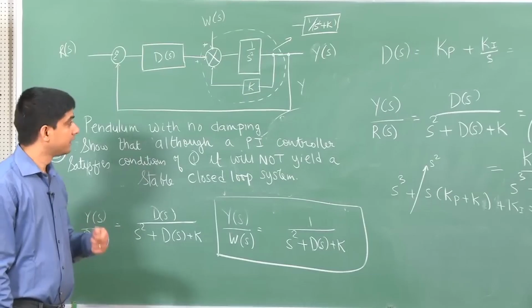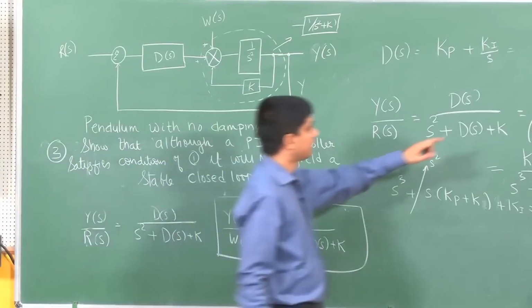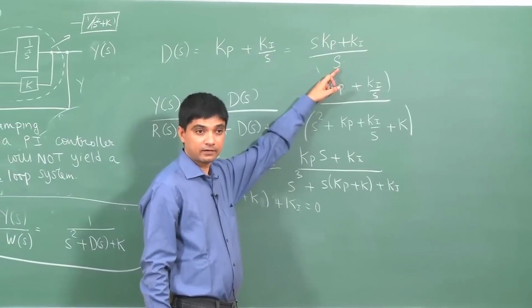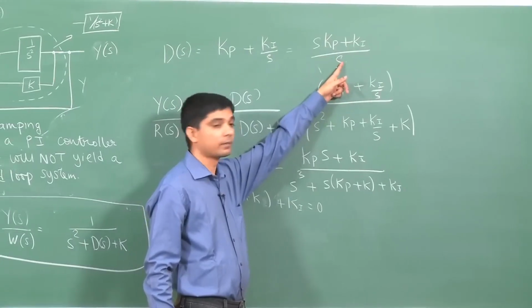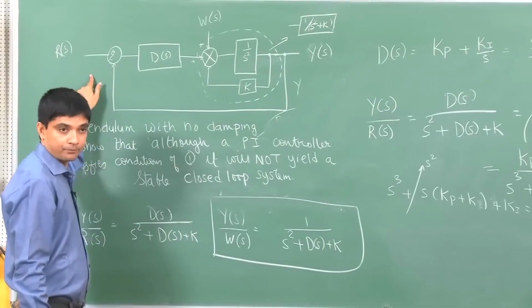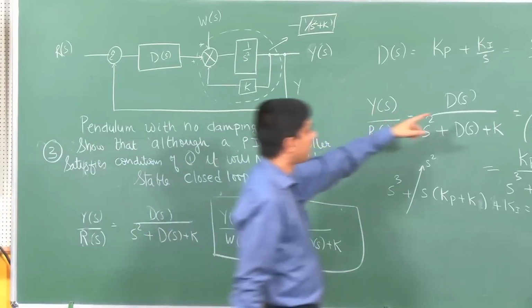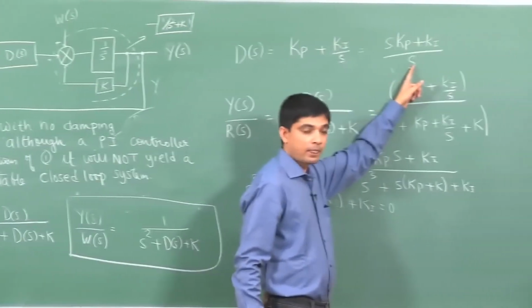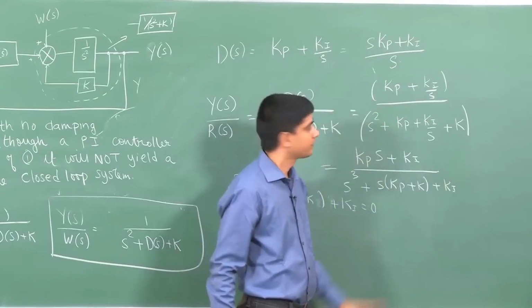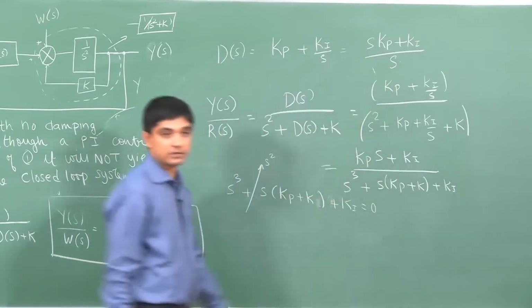And therefore, even though a PI controller has the effect of reducing the steady state error, if this was not true in problem number 1, this would never be able to track a ramp. So, by putting a pole at the origin, I see that I track the ramp but with some error, but then the closed loop turns out to be unstable.